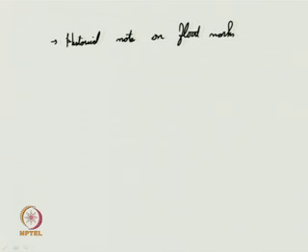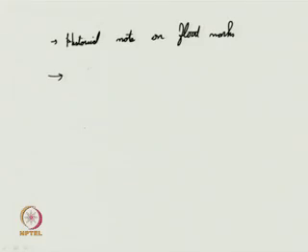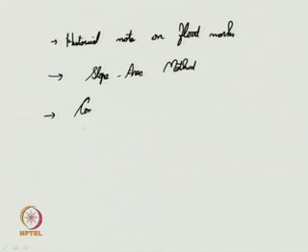During the lean period, this is the mark, so at various situations, what are the different flood marks. You can either capture them in photographs, or you can survey the marks and obtain them as data. Once you obtain the corresponding data, then you can use, for example, the slope area method, which we will see today, to evaluate flood discharge. Then there is another method called the contracted opening method.